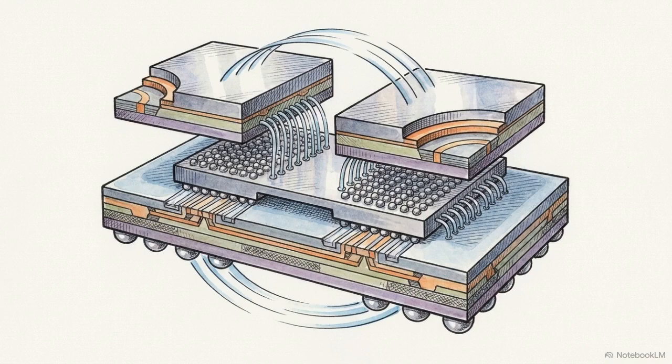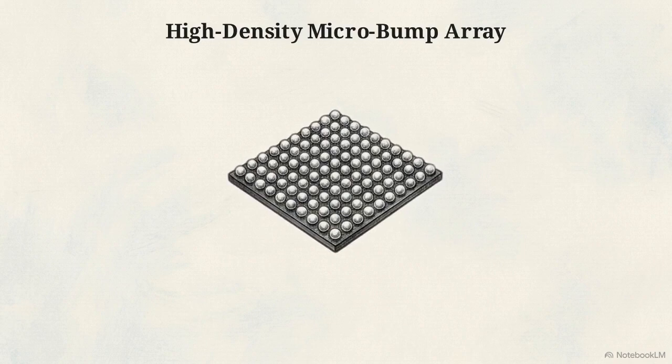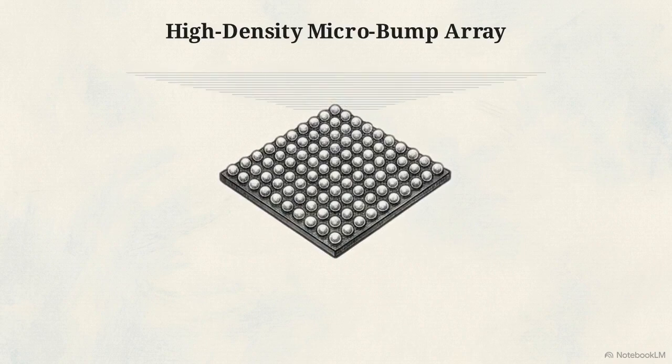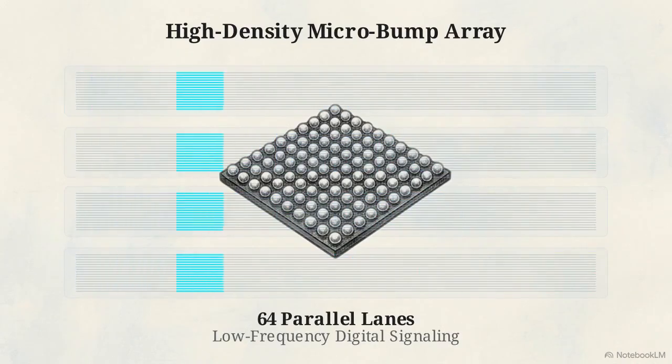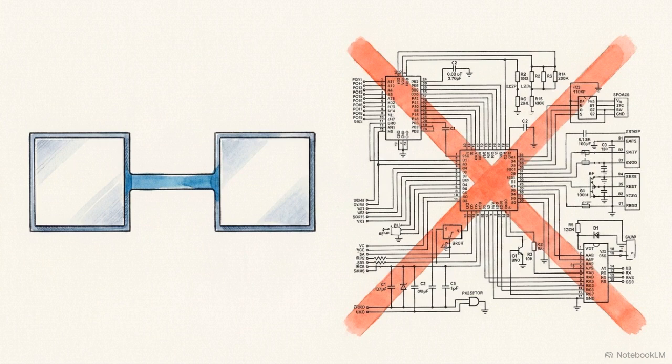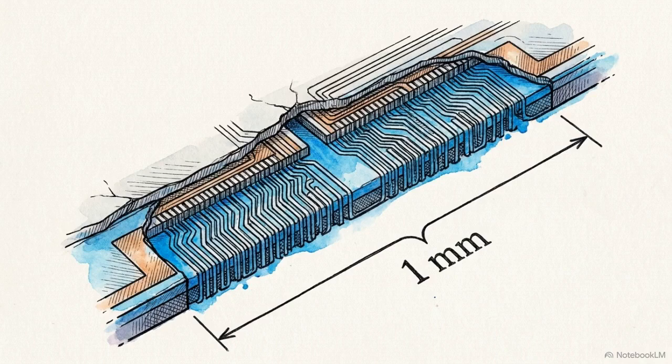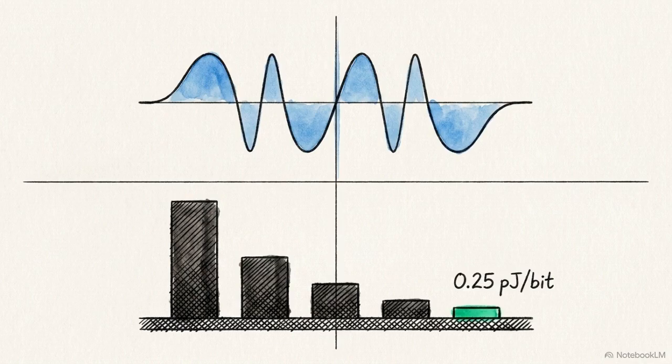The microscopic gap between two partitioned chiplets dictated the engineering of the entire UCIe standard. The tight geometry of microbumps allows for an immense number of parallel wires, resulting in wider data paths that operate at highly efficient digital frequencies. The physically short distance of those paths guarantees pristine signal integrity, eliminating the need for heavy analog RX termination and complex clock recovery circuits. The result is a standard that delivers terabytes of bandwidth per millimeter, achieves sub-nanosecond wake latencies, and drops base power to 0.25 picojoules per bit.